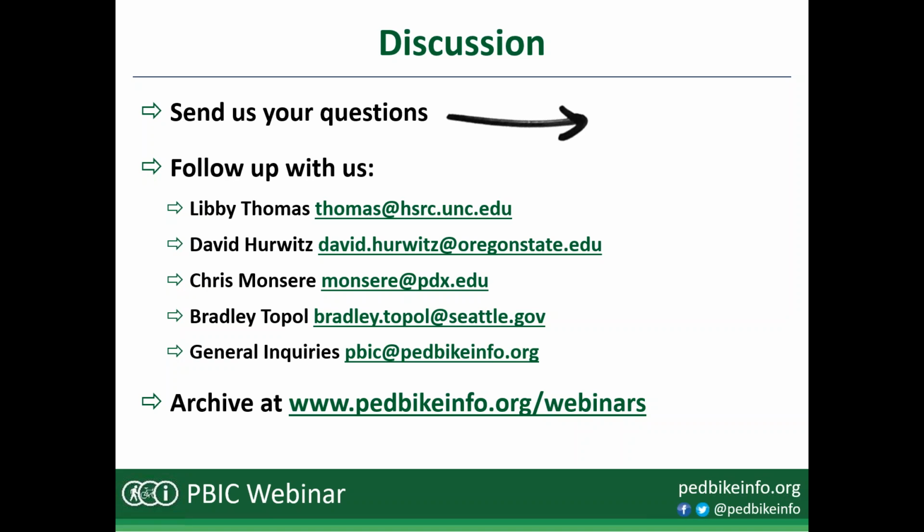pedestrian vehicular crashes. Beyond that, yes, we are still continuing to look at the existing crash data, like those downtown locations, to look at, should we do more signal separation? Maybe LPIs aren't enough. Now, we're starting with LPIs partly because funding can be tough, and this is a really cheap, easy first step. But we could continue to combine that with a leading pedestrian interval, and then maybe we come back and do a lagging left turn phase as well.